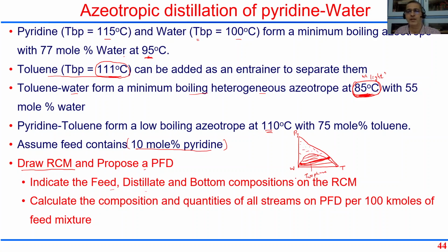So now, in addition to the residue curve maps, the location of this two-phase envelope, the two-phase region, is also very important. Okay, so draw this residue curve map, an approximate residue curve map, including the two-phase region. Pause the video and only when you're done, continue.